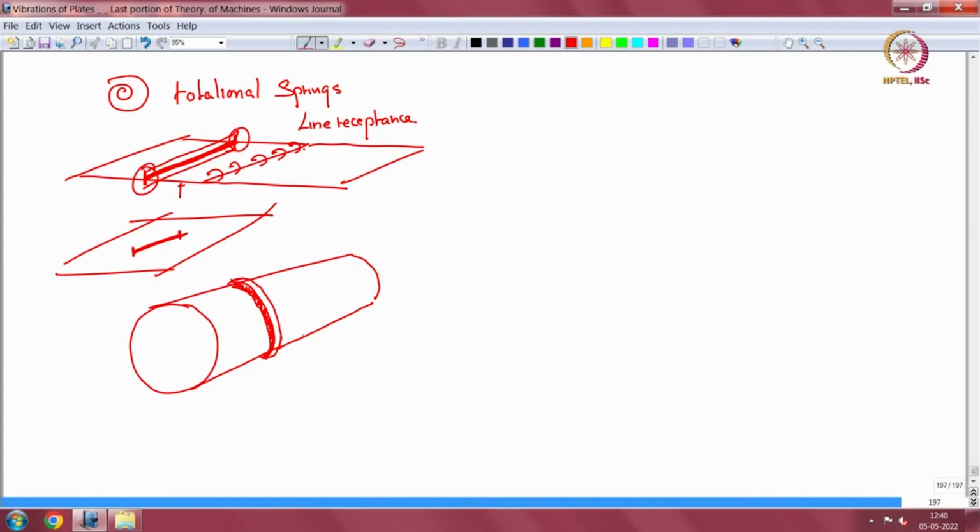Then the n that the shell goes through, either cos n theta or sin n theta, must be the same for the ring. If that is so, you can do a connection between the two and you can stiffen the shell. So we will look at stiffening of the shell in the next class. How to stiffen a shell using a ring, using the receptance method.